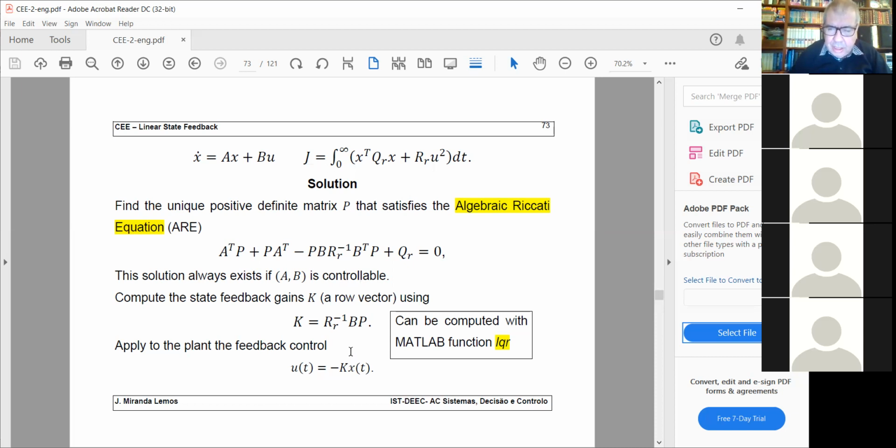And actually, the state of the pendulum is 4 or 5, can't remember. Because you have the position and the velocity, and then you have an arm that moves to equilibrate the pendulum, a rotating arm with a motor that gives you 2 more states. So at least you have dimension 4. And I'm just measuring one variable, okay? Which is the angle of the vertical pendulum.